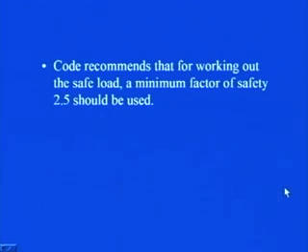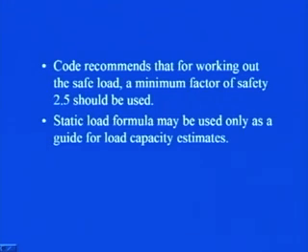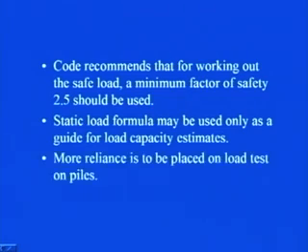Now, the code recommends that for working out the safe load a minimum factor of safety of 2.5 should be used. Then the static load formula may be used only as a guide for load capacity estimates, that is you really cannot rely on only the static load formula. More reliance is to be placed on load tests on piles.